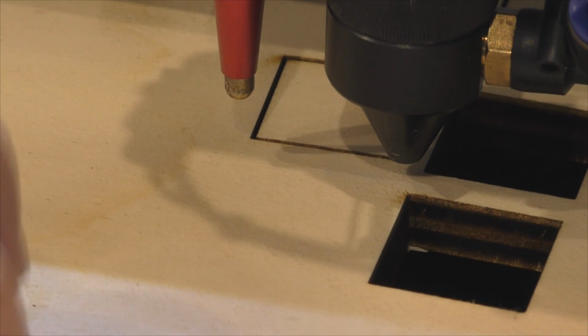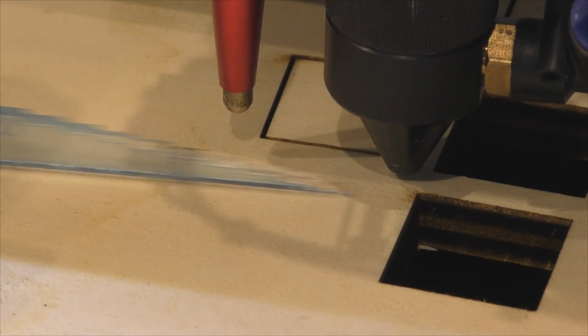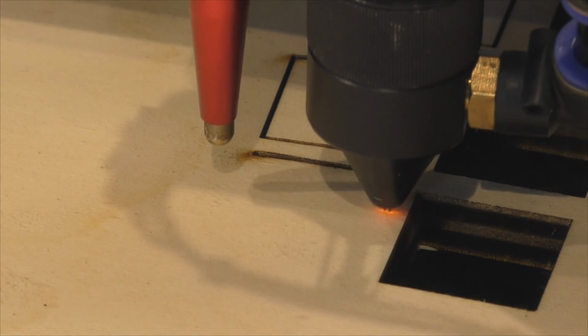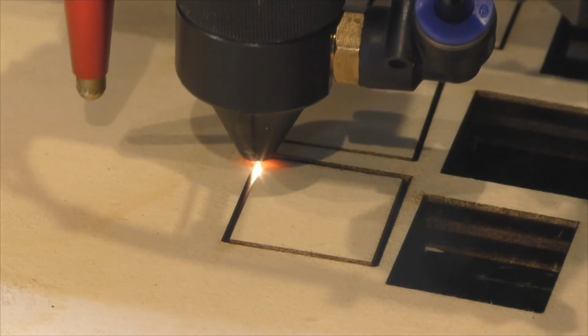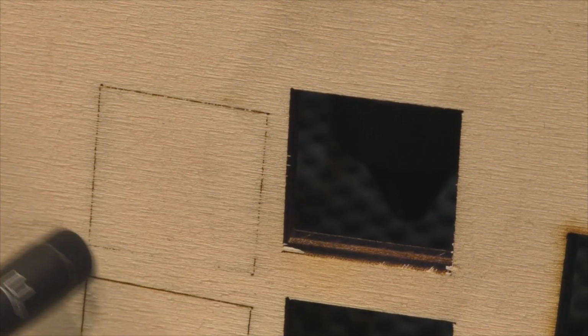This is 10 millimetre thick material, remember. Ideally we want to be somewhere between 1/3 and 1/2, so the book says, through the thickness of the material. We've only got a 5.5 gap, so this is 10 mil thick material. Let's go down another millimetre to 2.5. Well, to be honest, I don't think that's had any effect at all. I think it's got worse.